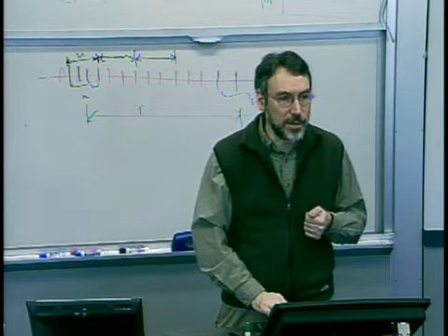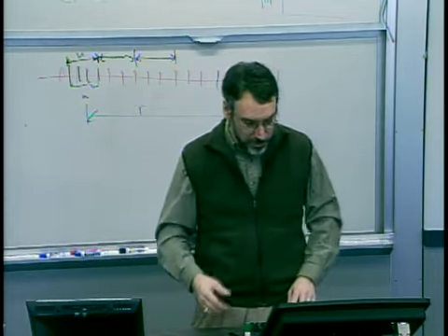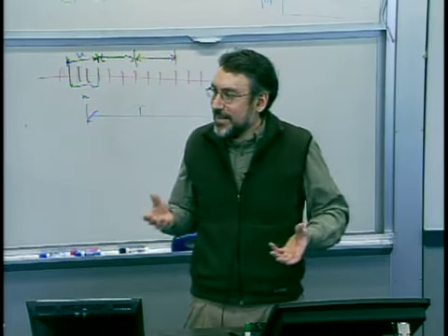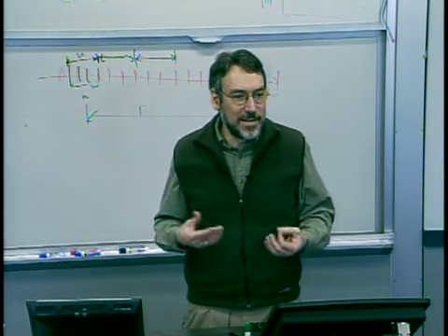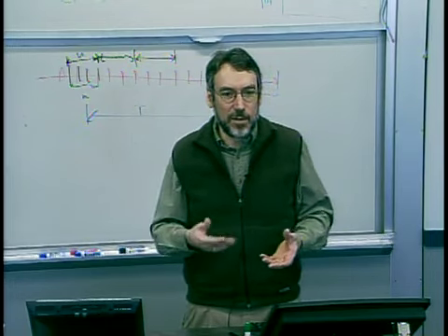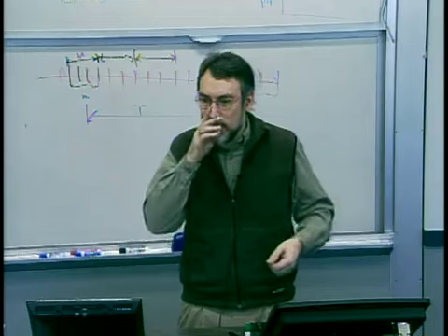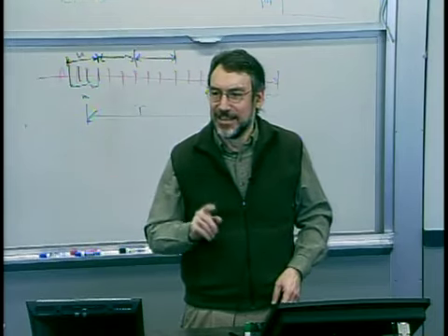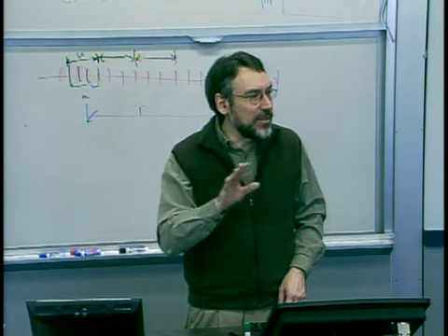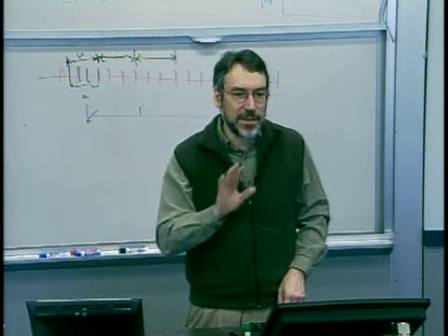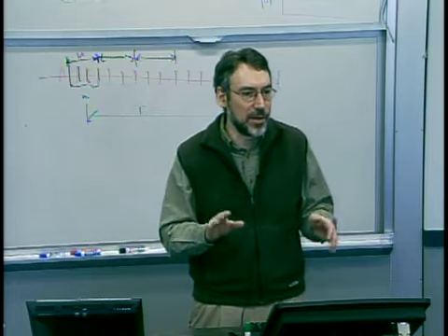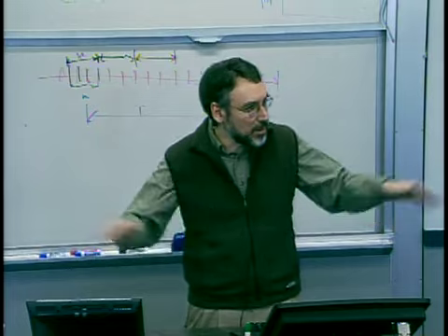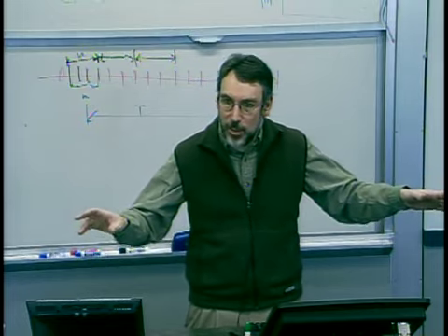Now, the last thing I want to do with the CP and CPK is give you a little bit of a qualitative feel for these, because what is a good value for CP and CPK? Well, the larger, the better, right? A CP or CPK of 0, that's not good. When you start getting in the ranges of 2, that's often what is talked about in manufacturing as being a goal. But it really depends on your process and what the costs of non-conforming parts are.